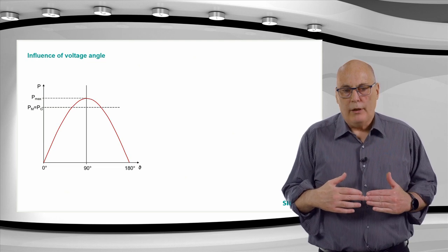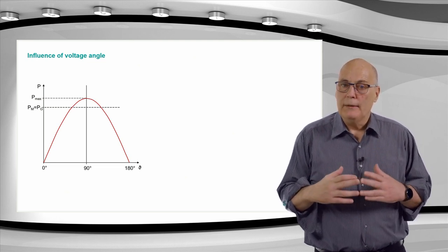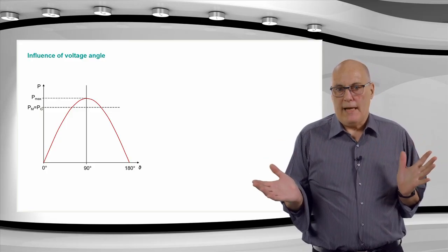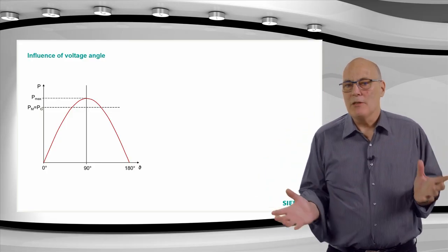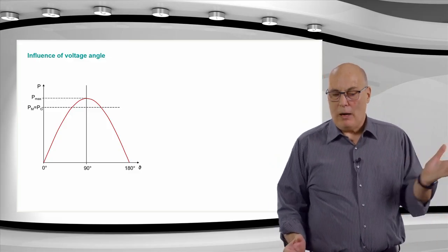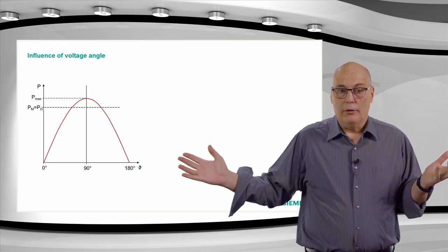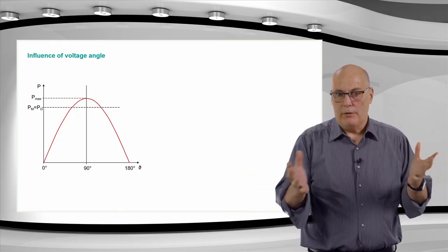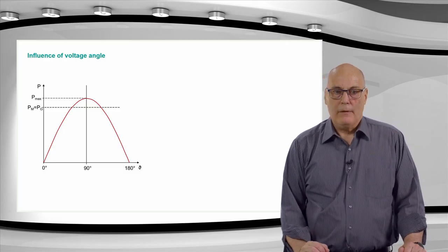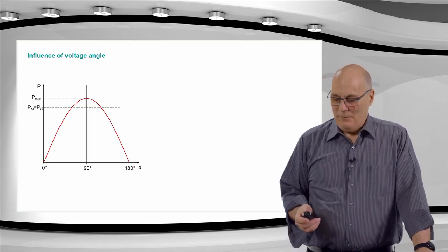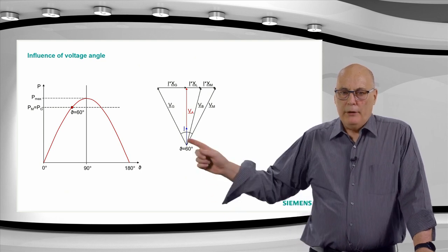The first thing we have to identify is that in a normal steady state operating condition, the PM and the PG are the same, because the network does not store any energy. So what power is coming in on the generator side into the electrical system must go out on the motor side. The electrical system, as we have defined it there, has no means to store power. So that would be a typical operating point, and we have drawn that here.